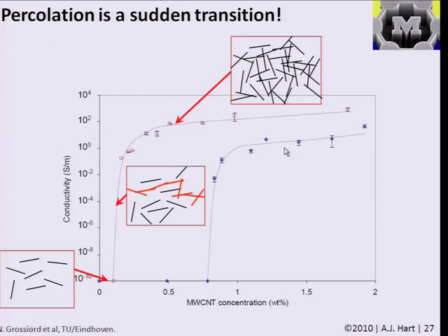But if we look at this case more formally, this is a typical plot of the conductivity of a film as you add stick-like conductors to the surface. And below the percolation threshold, before the concentration at which you have enough sticks to create this continuous path, you have essentially no electrical conductivity. Then at the concentration at which you form this first continuous path, the conductivity jumps dramatically.